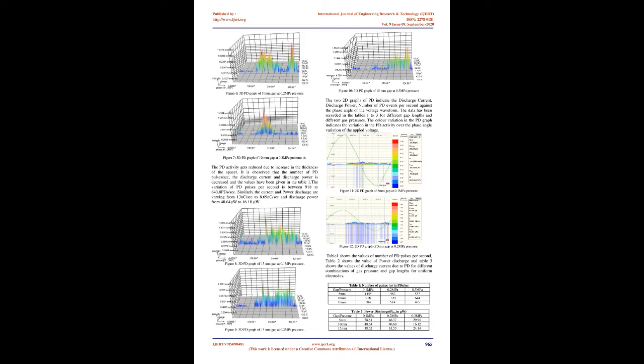3. Results and discussions. The experimental results of plain electrode setup with PMMA spacer with variation in spacer thickness at different gas pressures are as shown in figures 2 to 10. The chamber with electrode arrangement has the provision to fill the insulating gas of SF6-N2 gas mixture of 10:90, which is filled and maintained at different pressures.